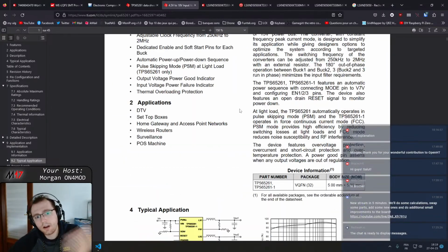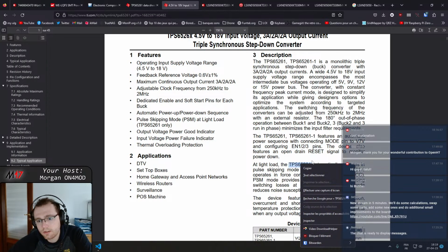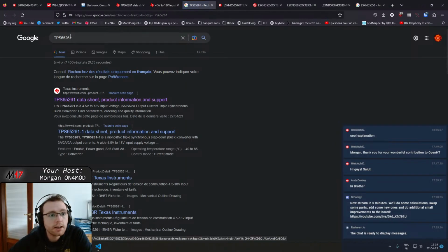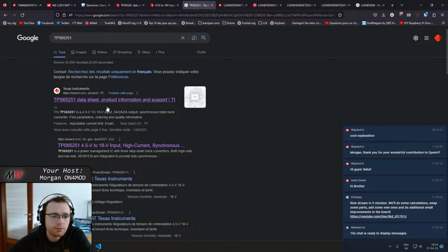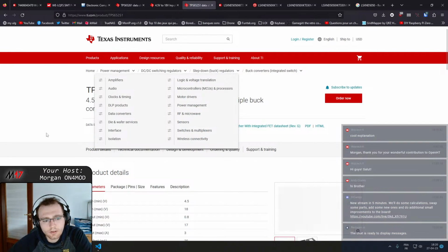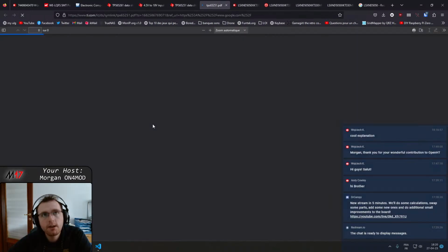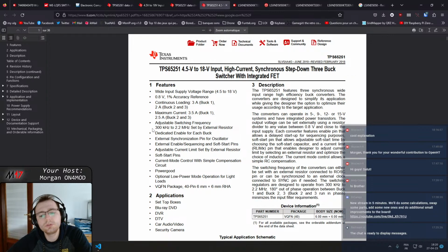Okay, so then how to fix the problem? Well, we'll have a look, and I'm just gonna pick a device which is very similar to it, which I first tried to use for this design, but I picked this one after that because the one we use does have a lower quiescent current, which is the current that the devices use when they are turned off. So basically battery drain when the device in the radio is in your drawer.